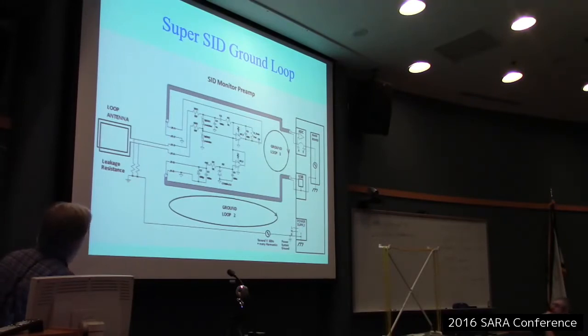Well, if you look at the situation, the USB in a computer does not do the best job of grounding things from an analog point of view. So you have your soundboard, which has an A to D converter here, and it gets a ground where on that board it's grounded to the digital ground for the computer. The USB has its ground at a different point, and you've got signals all over the place on a computer motherboard of many millivolts, which don't bother the computer. However, for something like this where you have a sensitive instrument, it's not a good idea.